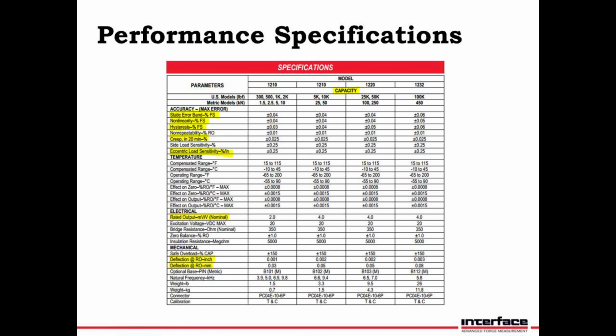If you go towards the electrical, if I'm not mistaken, sorry, under temperature, we can see the maximum error associated with the temperature effect on zero balance. And towards the bottom, we can also highlight in yellow some of the maximum deflections that load cells are designed to withstand.